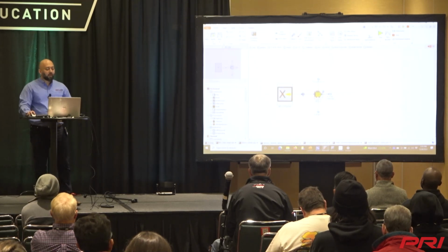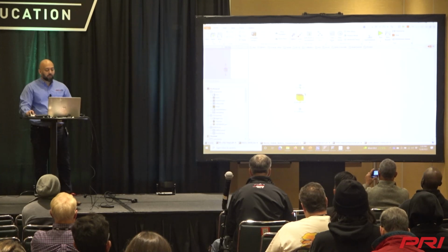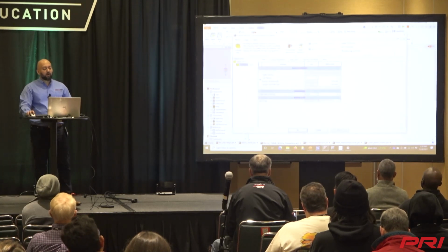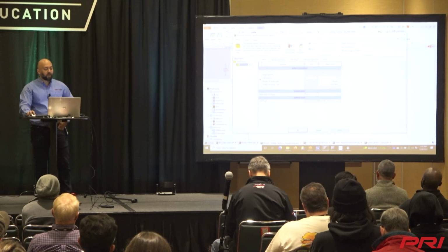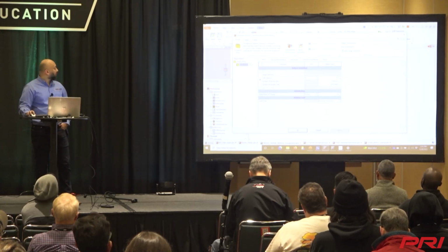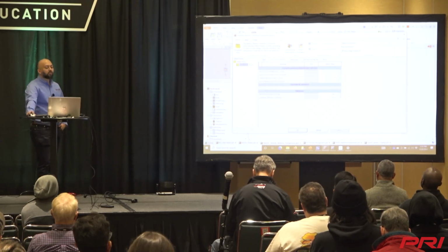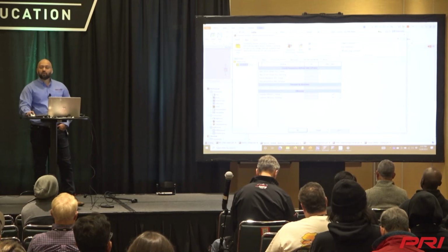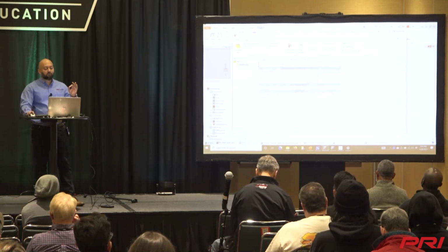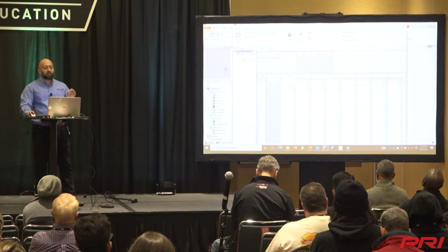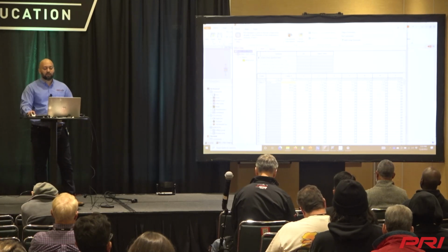The way the motor gets power is from the battery. In this case, the way we have created the battery is by using electrochemistry: number of series cells, number of parallel cells, and then we determine the open circuit voltage for charge and discharge and internal resistance for charge and discharge for each of these single cells. Here on the x-axis you will have battery SOC, and on the y-axis you have different temperatures of the battery, as that's going to change what the open circuit voltage and resistance look like.